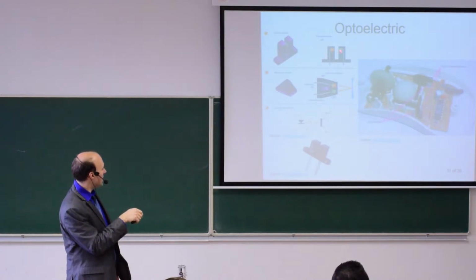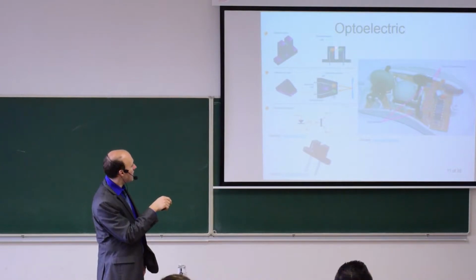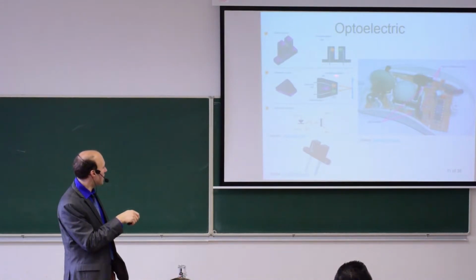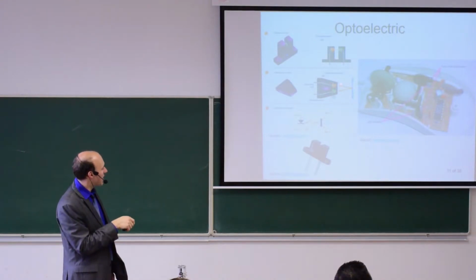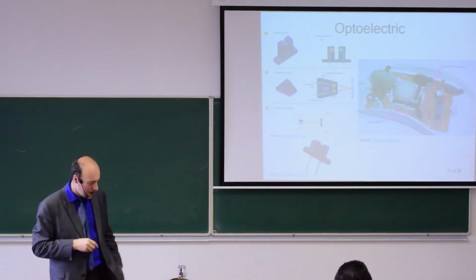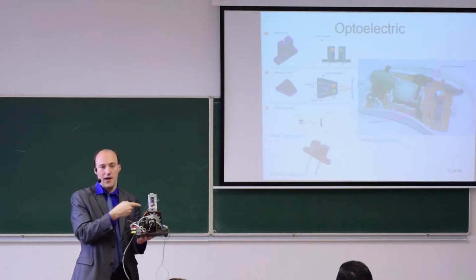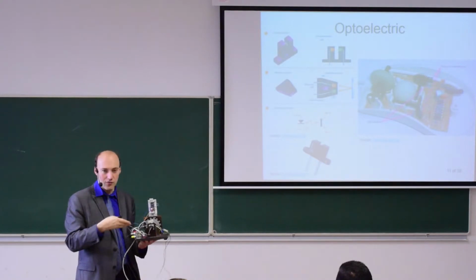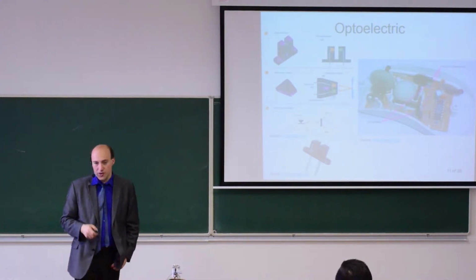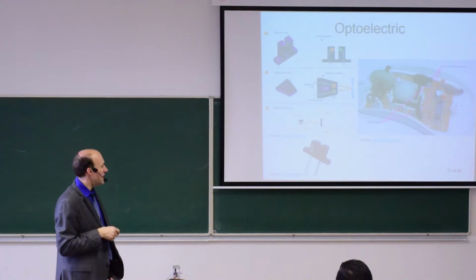The sensor can look also like this. This is an integrated pair of LED and phototransistor or photodiode, and then the disk is moving in this slot, and you can count the pulses and get the speed. It can also work in this way. This is a reflective sensor. It's a package where you have the LED plus the phototransistor in one package, and you're looking for a reflection. If this were installed, for example, in this application, then I could look for reflection from this sticker, and I could get, again, a rectangular signal, and I could measure the speed of this disk. So both approaches are used. It depends on the application, but I would say that this is a more common approach where you block the light with some material that is moving or rotating.